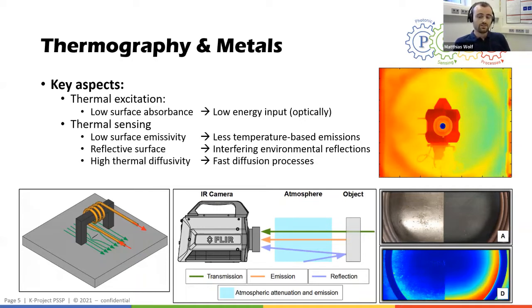These key aspects are already challenging in some cases, even if the object is stationary, but are especially challenging when it comes to measuring moving objects using thermography. There it is necessary to provide additional preparation, for example, to use an inclined camera viewing angle, or to cover surrounding infrared radiation to provide rather uniform reflections in the field of view.